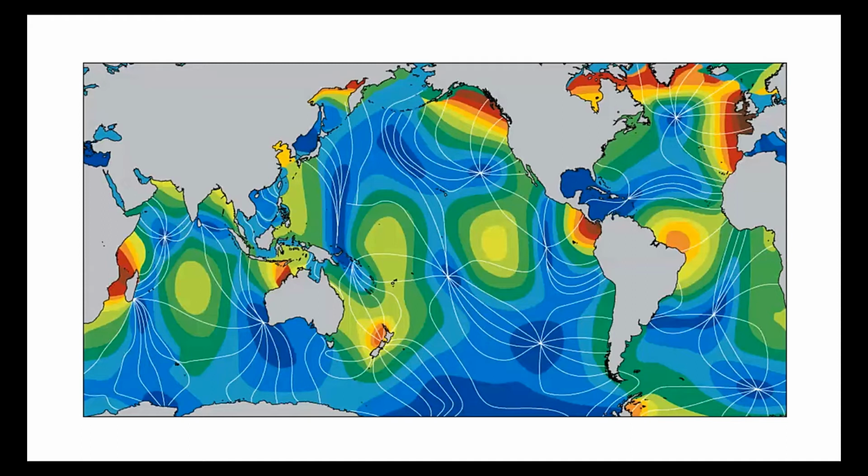All sorts of things have been tried. I've seen funnels as well, and I've seen a simulation where they let the turbines go wherever they want to maximize power. What ends up happening is that the turbines do actually form kind of into funnels. But those turbines themselves are producing no power. They're just forcing flow into the center where there's a wall of turbines waiting for that flow to come through. So there's the possibility of maybe even putting in barriers to try and funnel this flow into certain areas, things like that.